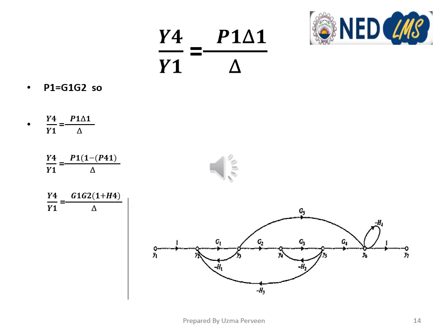Okay, now after calculating the value of Y2 upon Y1, next we'll calculate the value of Y4 upon Y1. Y4 is again a non-output node. The procedure will remain same. First we'll see the forward path, which is from Y1 to Y4 this time, and then the value of del will remain same, and then we have to calculate del i's.